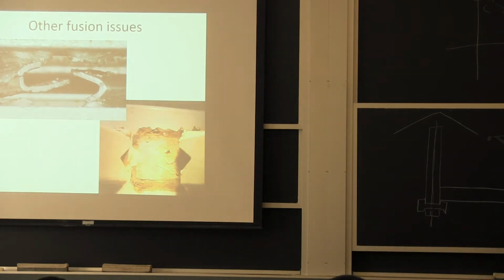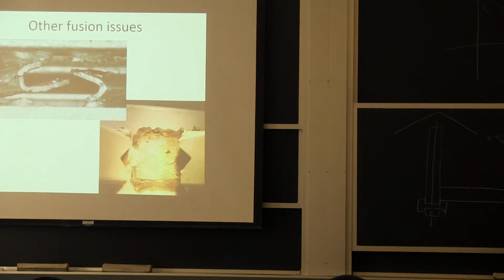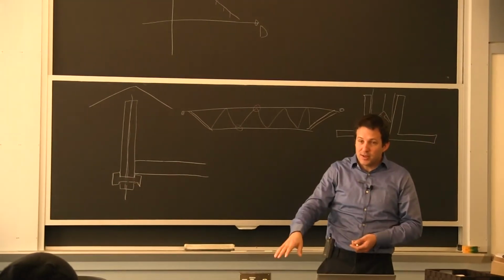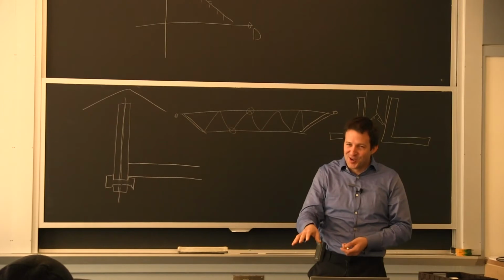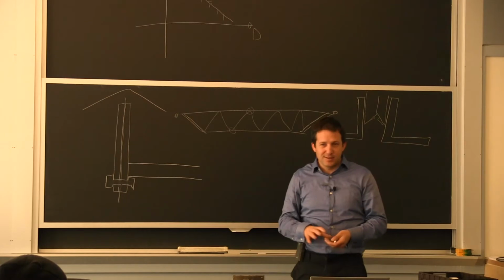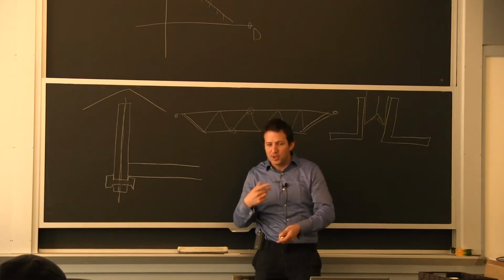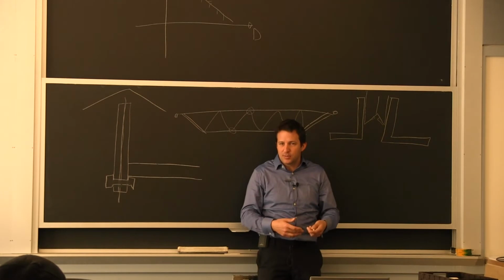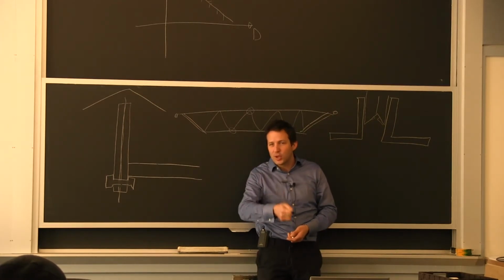Anything else on welding? Because we're close to the end of the session. And it's great that those things come up, because in any welding procedure, that's what I worry about the most, that a guy is going to try to go too fast and he's not going to be able to melt. What I've been trying to do sometimes for a critical application is select the welding process that they can't go too fast. With a stick electrode, it's a little harder not to melt. It can still be done, and if you tell them a certain polarity, it's even harder. If you provide more heat to the base metal, the electrode's not going to go away and you'll be able to do it.